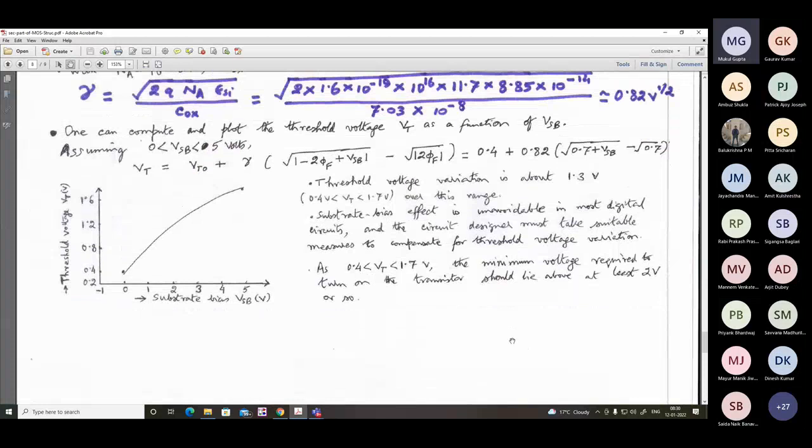Not like that. If we take the gate voltage to be 0.4 volt, you see that for some application, gate and drain may need to be shorted, right? So drain is connected to 5 volt, then gate is connected to 5 volt. Yes, that means you can take the maximum range to be 5 volt or even higher. It is assumed that in general, source is at a lower potential with respect to gate. So maximum voltage should definitely be above 5 volt, right?